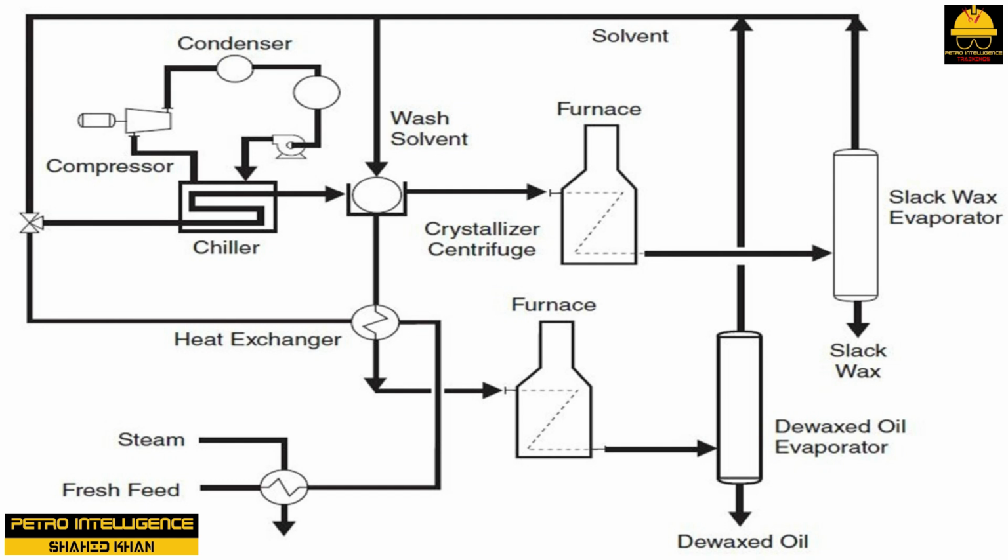The filter used in step 2 is a barrel made of a coarse metal mesh. The mesh is covered with cloth. The lower portion of the filter is in the oil and wax mixture. The filter turns slowly. The wax builds up on the cloth. To separate the oil, a vacuum draws the oil and solvent through the barrel. The barrel collects the wax on mesh surfaces.